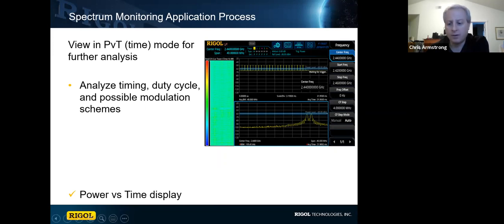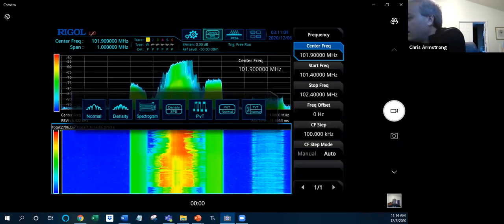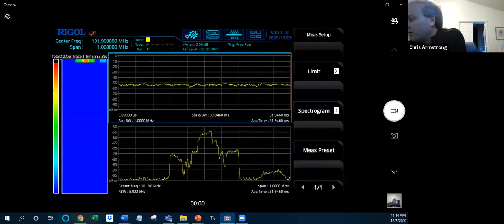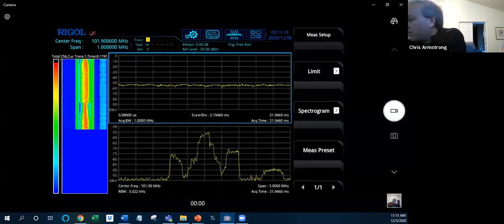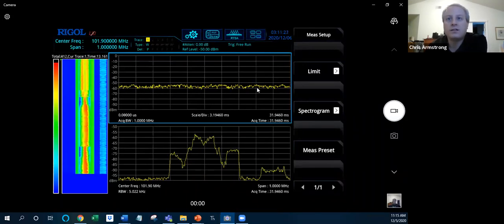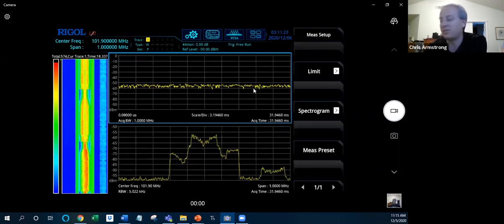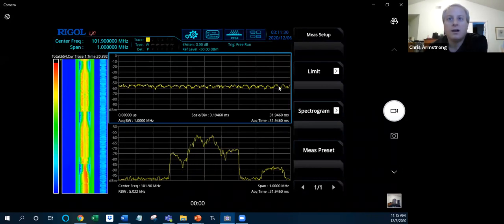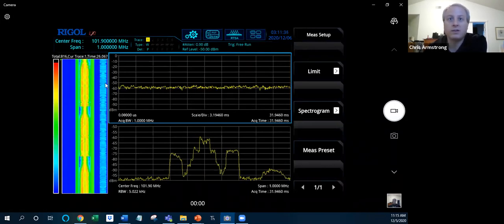Now, if we do that with our frequency signal that we have built in here, it shouldn't be terribly exciting, but I'll do it anyway. So now we can see that. As you would expect, it's an FM signal. So within the band of the detector, the amplitude is roughly the same across the board. It'll change a little over time depending upon what song's playing here, but in general, it's not really time demodulated, right? It's moving in frequency space. So it's best to view in this waterfall arena.